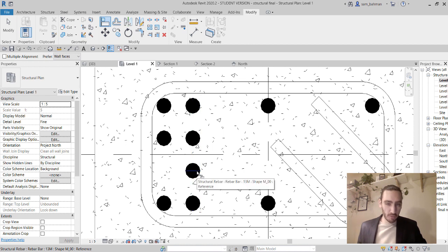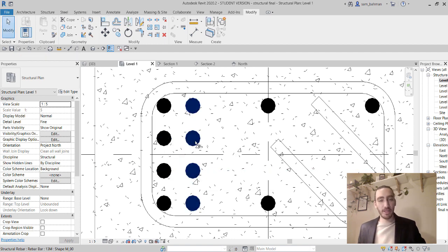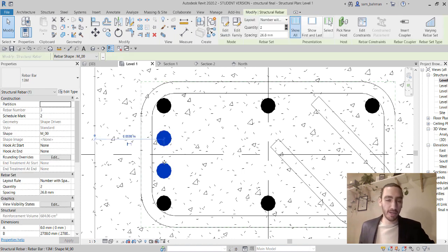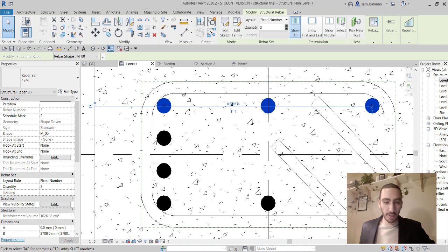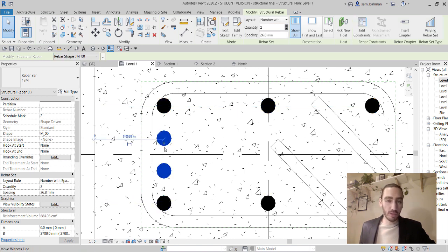Just simply bring the point viewer till you find the horizontal snap there, and with this one as well, click on OK, and now you would be able to delete this one, and this one is getting perfectly placed there. And as you can see, there is no longer any sort of repetition happening there. So this rebar is simply working with this one, those ones are at the proper place, and these ones are only independent of the others. Cool, so it's perfectly working.